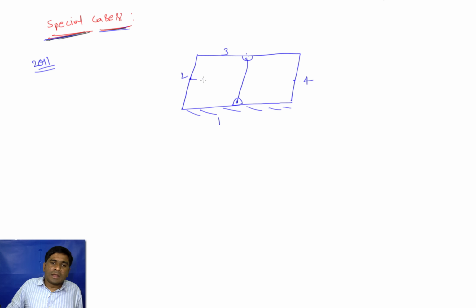So whether you join like this or join like this, if these joining points are at the midpoint, and not only midpoint, for example, if you are joining at a distance x from the point A on the link 3, and here if you take a distance of x from the point B on the link 1, and if you join, even in this case nothing will happen, because whatever distance it travels is equal to this one.